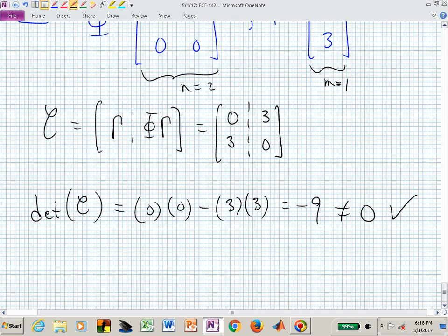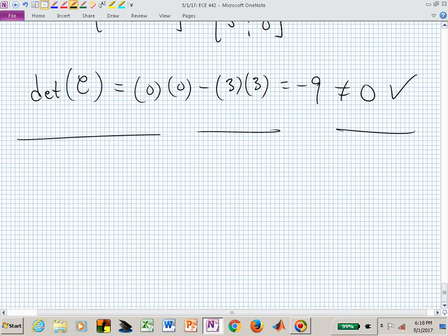So, in fact, that choice of 0.8 plus and minus j 0.2 for closed loop poles could have been anywhere we wanted in the unit circle. And we could have found values for K1 and K2 to make that happen. That's what this controllability check allows us to conclude, which is why typically this is what we do first. We immediately check, is our system controllable?